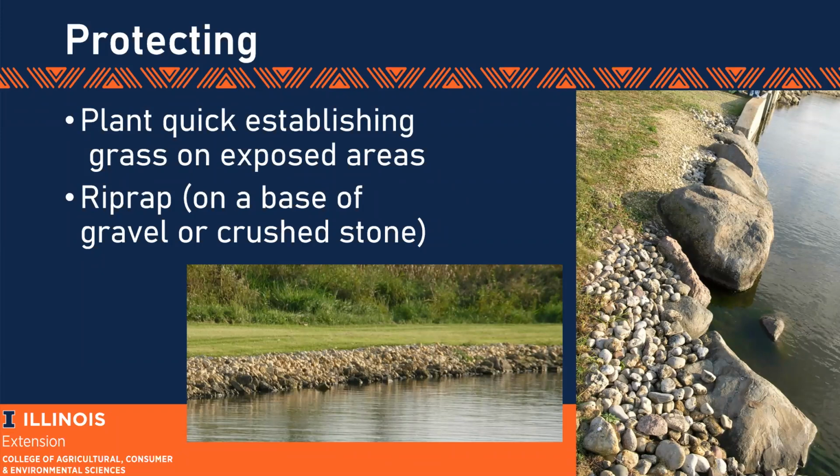Along that same pond, over on the far side, so this would be the south side, the larger picture on the bottom, you're looking at the south side of that. They put a few larger rocks in there, but more of a moderate-sized riprap with a gravel base to absorb some of that energy. And also it's pretty steep, so it keeps it from eroding and sloughing off, limits how much plants will grow up in there, and is a good way to keep some of the plant material out of the pond. Kind of gives you an idea when we talk about somewhat steeper slopes along those edges.